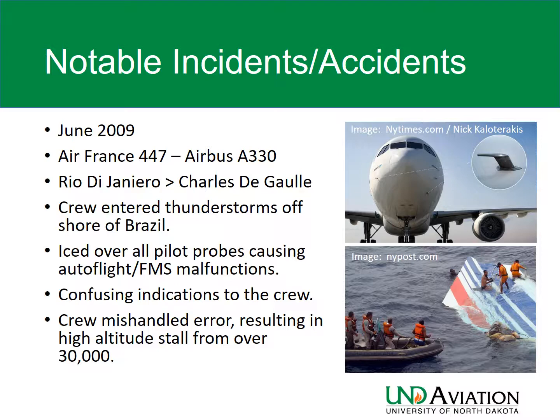Fairly soon into the flight, the crew encountered thunderstorms while out over the Atlantic. They entered a condition which caused severe icing, and the probes were iced over despite being heated. Those probes, those pitot probes, were iced over during an encounter with severe icing. And due to multiple probe failures, this caused confusing indications to the crew as well as confusing indications to the FMS, the Flight Management System, and Autoflight.